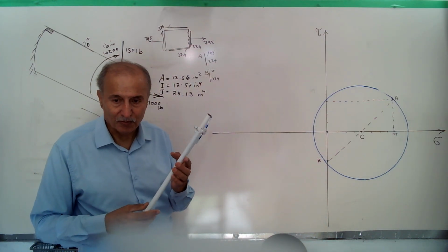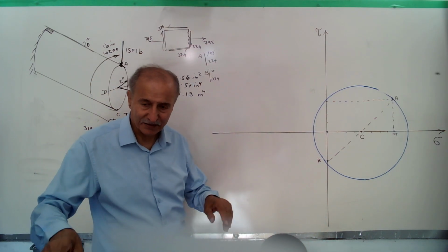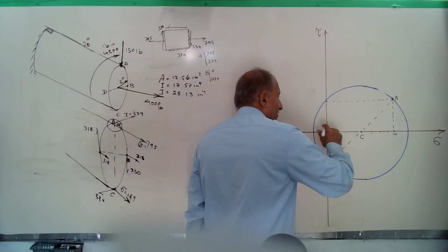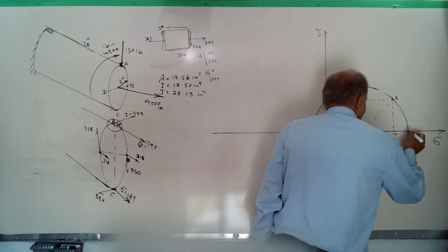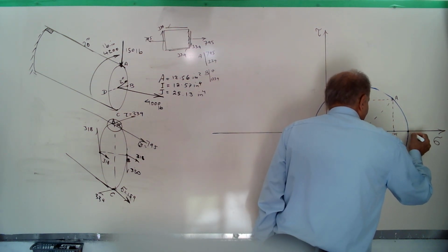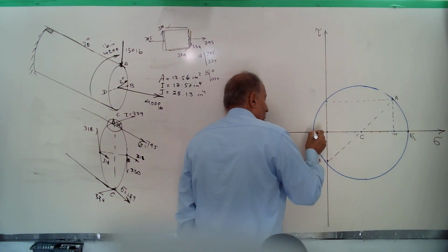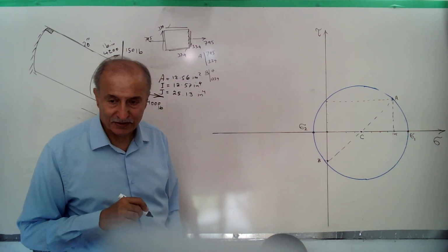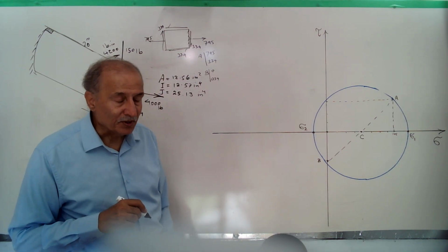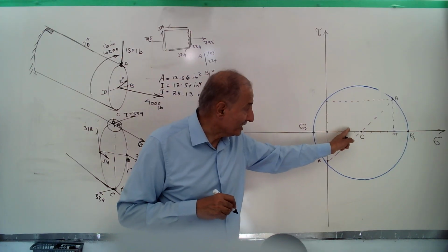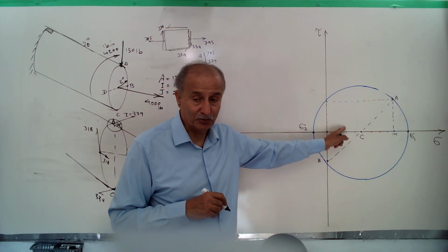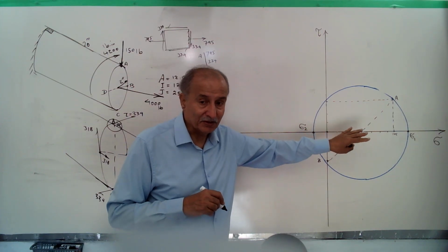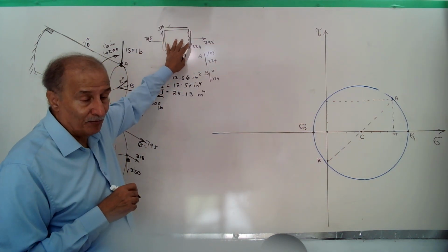It's not touching, we must pass B as well. Okay. We accept it. Then it intersects the horizontal axis, sigma, at 2 points. One of them is called the largest, sigma 1, the smallest, sigma 2. These are called principal stresses. These 2 points make 180 degrees on Mohr circle with respect to each other. Any angle on Mohr circle is doubled with respect to the angle on the element.